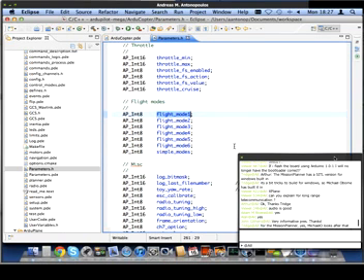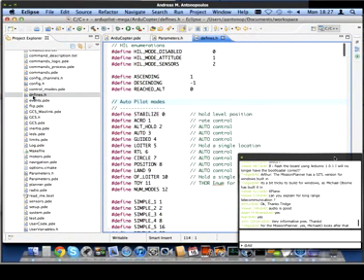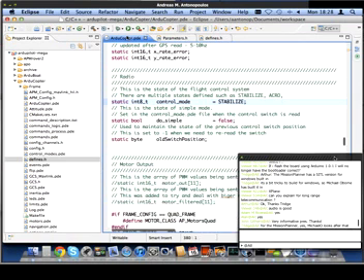So there you are. Those are the 6 positions where the Mission Planner is storing the actual flight mode that you've requested for that position. A little number will go in there from about 1 to 10 or so. What those numbers mean is defined in the defines.h file at line 114. So when you select, for example, loiter, number 5 would be written into that first parameter.